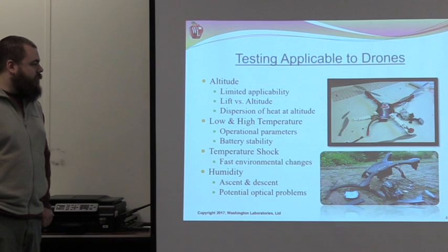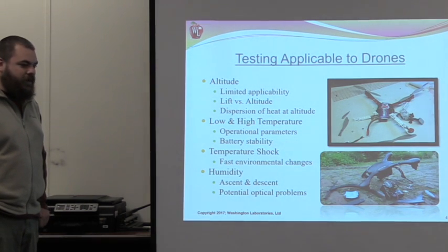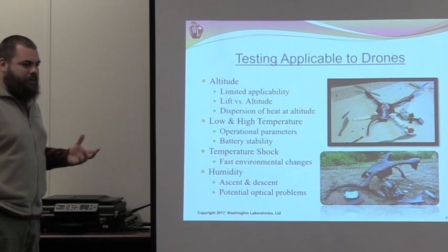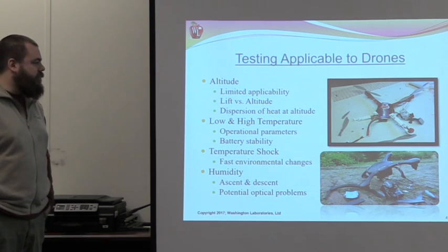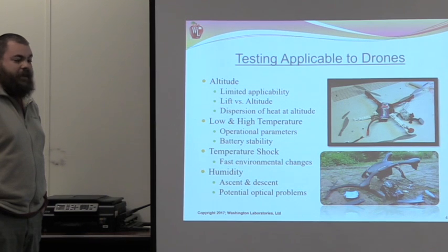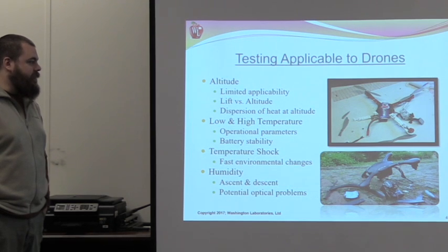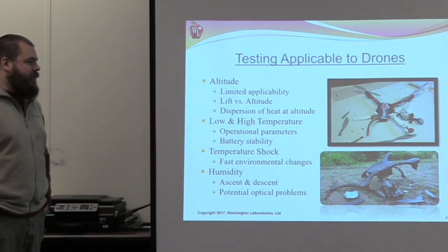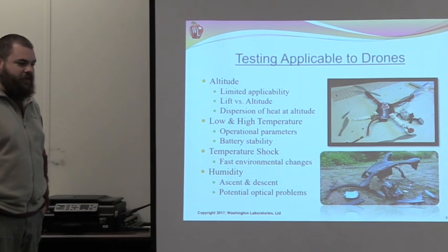High and low temperatures is also somewhat similar. Beyond very basic envelope parameters of what you've designed, your boards, your batteries, lithium batteries especially, there's not a whole lot of temperature things to worry about. You've got to remember that these are going to be flown in conditions that people are comfortable at. So you're not going to be out flying a drone likely at minus 40 C or 140 degrees. It's just outside the design envelope. So as far as component selection, it plays a part. In general testing, probably not so much, at least as far as the extremes go.